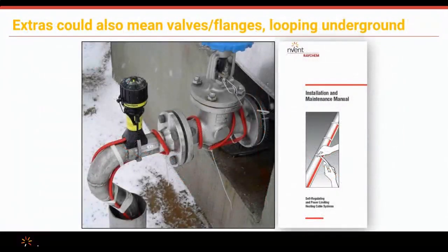Other extras. This is a big one. Valves are more heat loss. So we do have to wrap our heat trace cable around those valves. In our installation guide, we do go through very specific steps in how this is done.